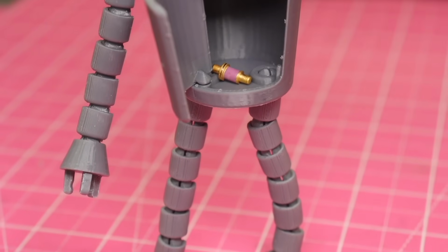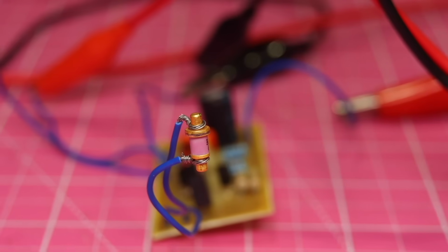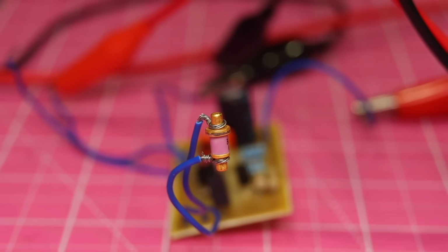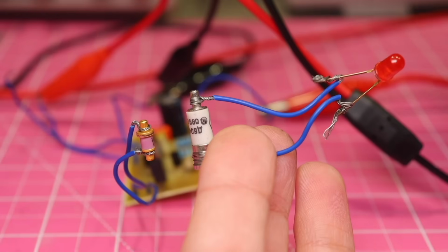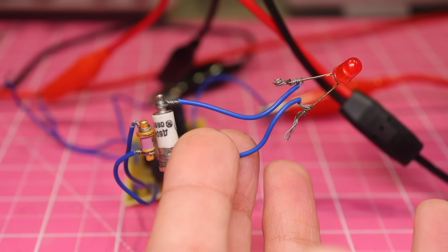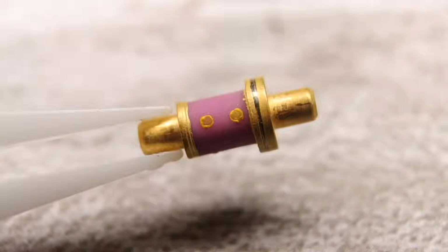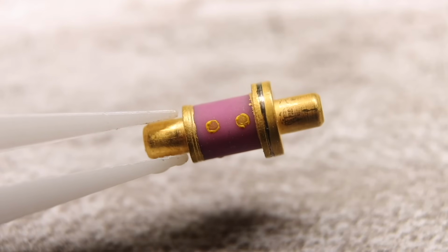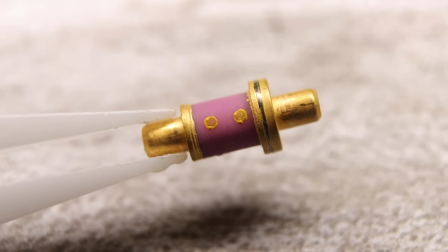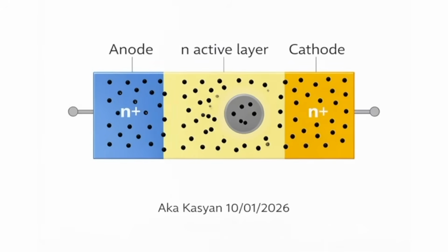In the case of the Gunn diode, as the external voltage increases, more and more of it drops across the domain, so the average current decreases. It is also important to emphasize that when operating in the classical domain mode, there is only one domain present at any given time. This, in simple terms, is the Gunn effect. But the question remains, why do domains form, and what is the nature of this phenomenon? Let's get to the bottom of it.